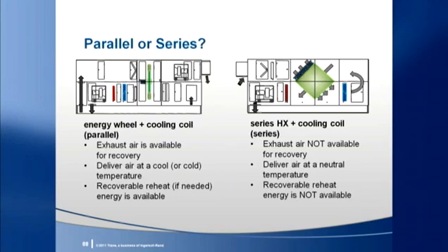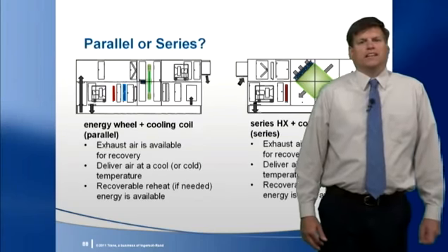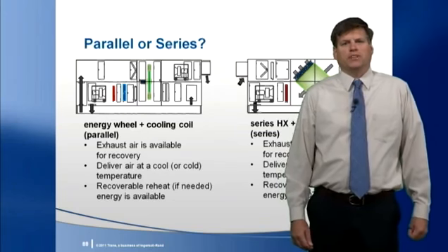However, there are applications where the series configuration might make more sense. If there's a need for neutral temperature air and there is no recoverable source of reheat energy, this might be a good choice. Note that it might take analyzing a couple operating points over the year to decide which works best for the application at hand.